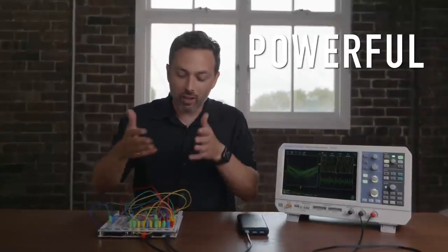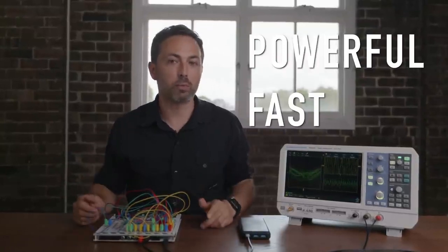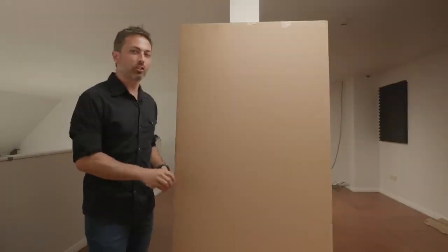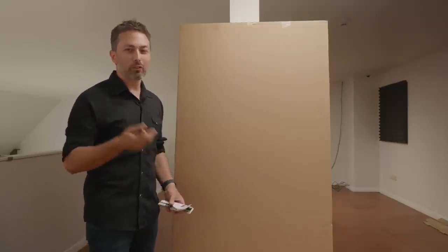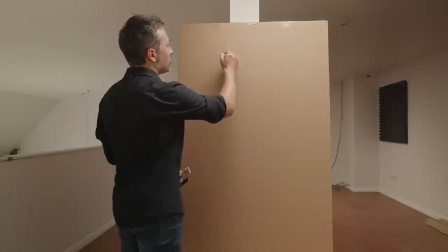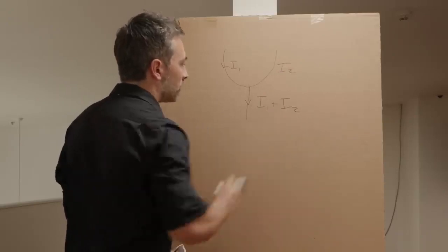So these examples illustrate some of the advantages of analog computers. They are incredibly powerful computing devices, and they can complete a lot of computations fast. Plus, they don't take much power to do it. With a digital computer, if you want to add two 8-bit numbers, you need around 50 transistors. Whereas with an analog computer, you can add two currents just by connecting two wires.